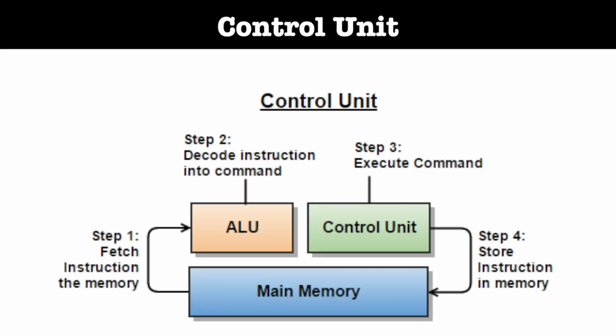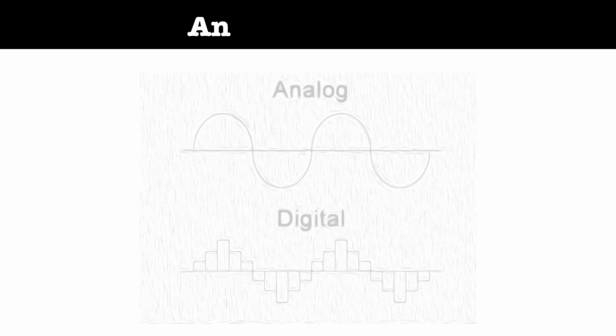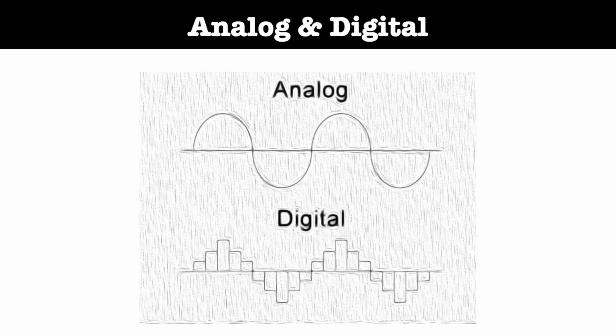The complexity of the control unit depends on the desired performance of the drive and the type of motors used. A controller can be a simple one consisting of few op-amps or few digital ICs, or it can be as complex as the combination of several digital signal processors, DSPs. So, the type of main controllers can be as follows: analog, which are noisy and inflexible, but analog circuit ideally has infinite bandwidth.